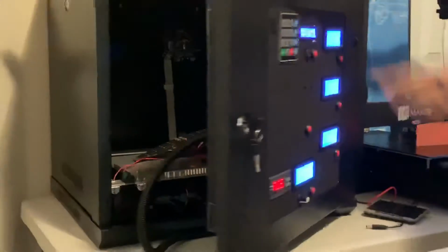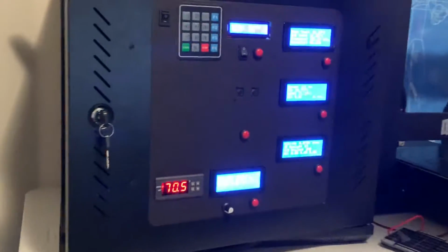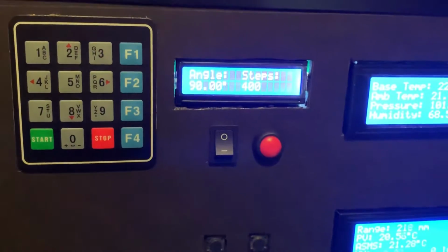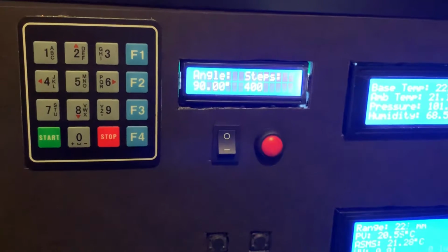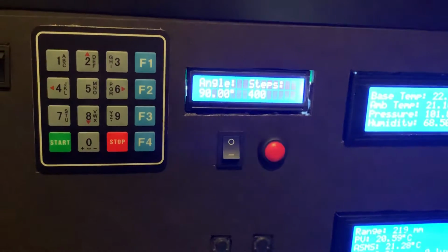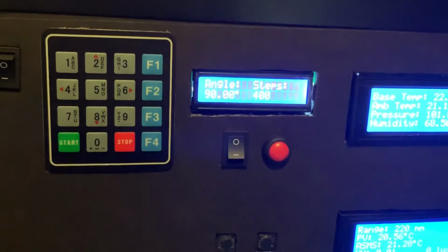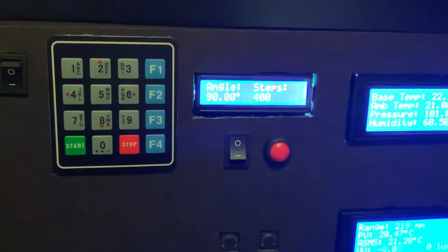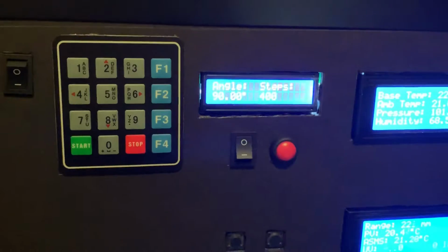So you can close this up, and then you can take a look at all your data. I talked about my beta angle position and control subsystem first, my BAPSYS for short. It converts steps from 0 to 800 steps into an angle resolution. Right now, I can get within 0.225 degree resolution for my beta angle analysis. I use this CNC device interface in order to conduct that base conversion, or step to angle conversion.